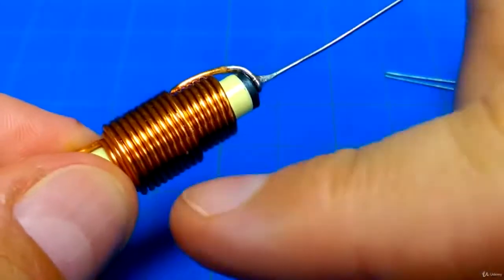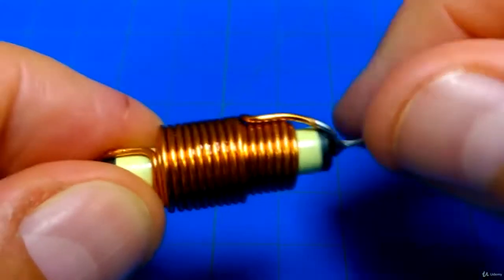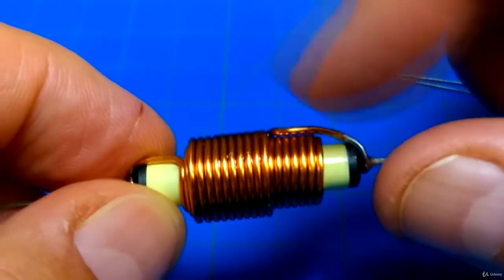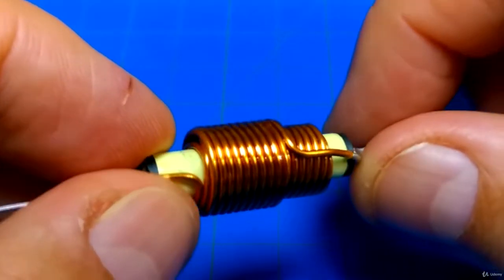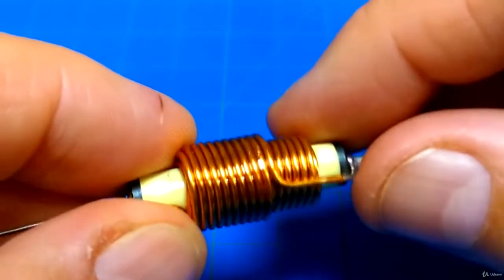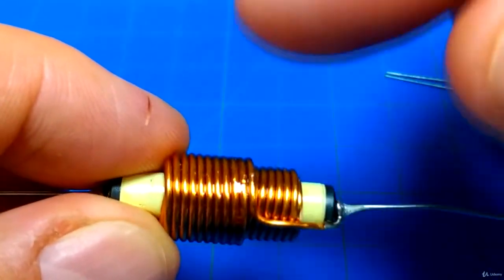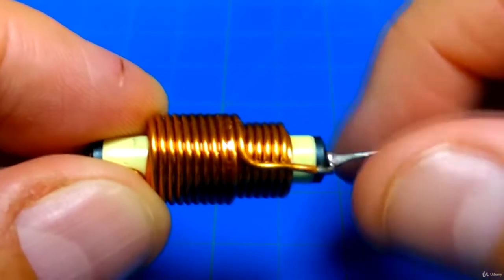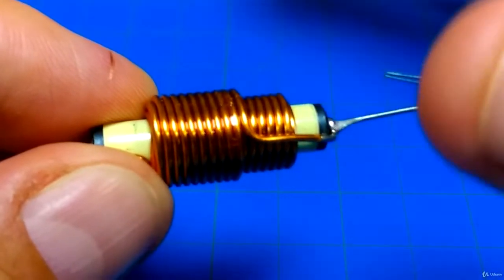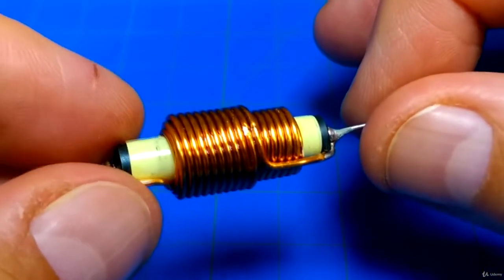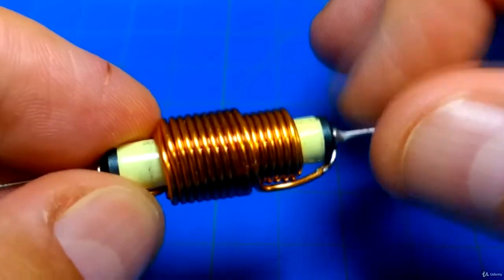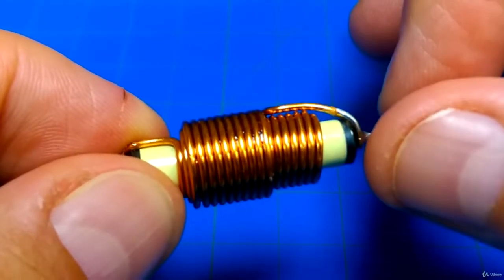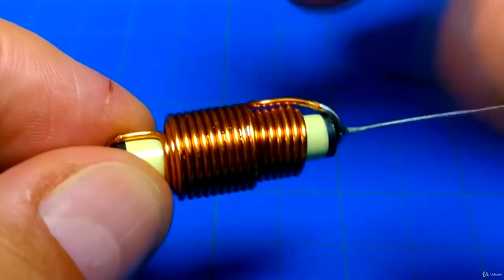All right, but now this is kind of weird. This wire is just touching each other, right? It looks like it's shorting. Actually, it's painted, or it has a kind of tarnish on it. So there's a coating on here, and that protects the wire. The reason we do that is we want to wrap these things as tight as possible, so there's no insulation other than a thin coating. Maybe that coating is a couple thousandths of an inch thick, or a thousandth or even less, and that protects it so there's no shorting. But you can get more coils in the same amount of space, because if you have insulation on the wire, then you're not going to be able to do that.